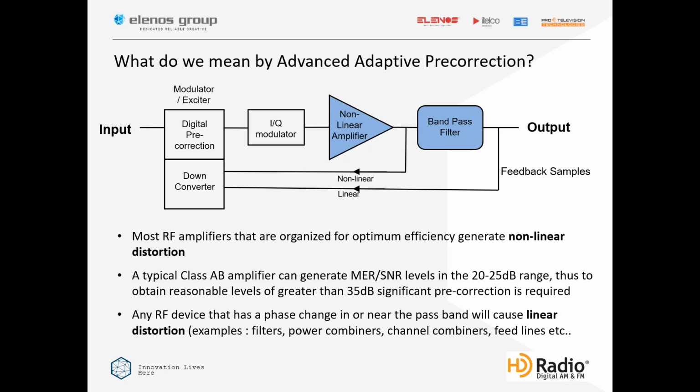But what he was explaining was that typically on a radio system, you have a nonlinear feedback sample that you then correct. And if you do have any filtering components out of bandpass filters and so forth, you take a sample after that, and that was able to correct for any phase errors in the system. So the correction system that Morten has put together can do both linear and nonlinear at the same time, and this really does do a great job at improving the signal to noise.